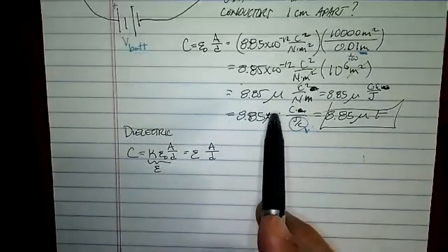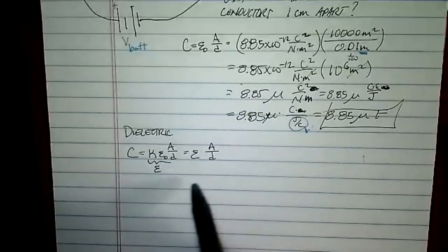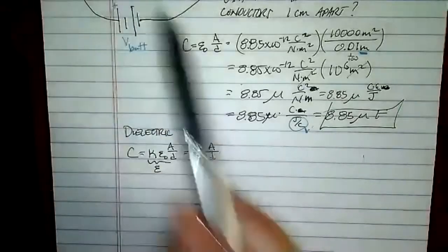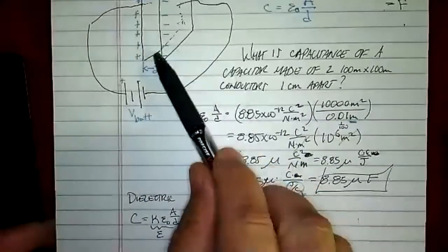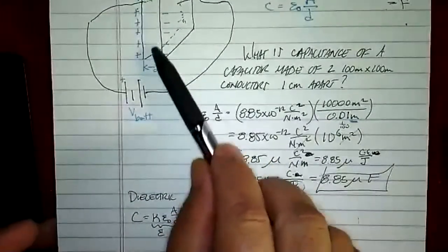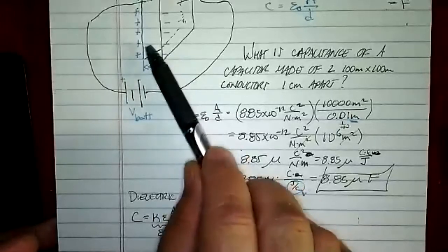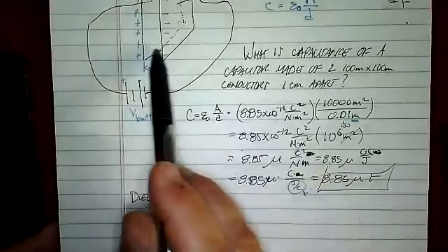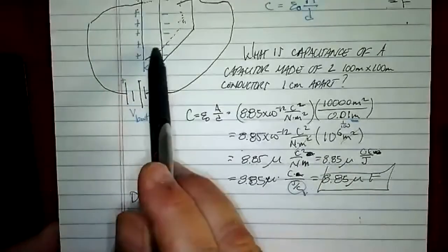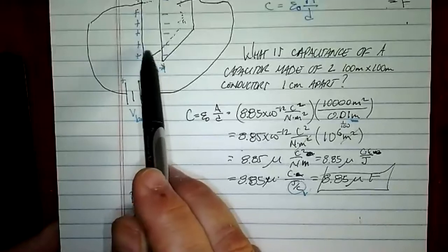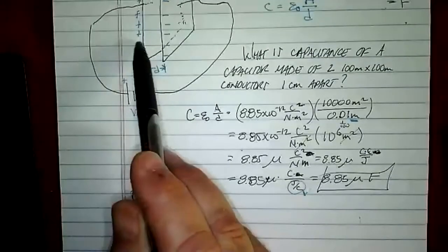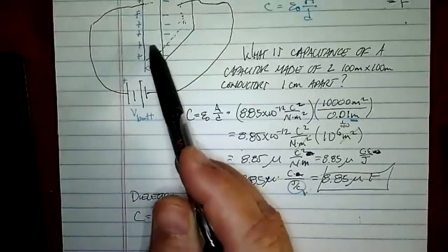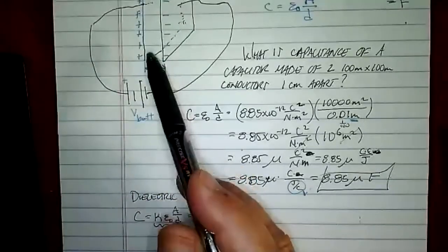So yeah, you can actually make it a lot better, meaning it can not only act as a mechanical barrier to keep the two plates from getting squished together, by filling it with neoprene or polystyrene or something like that. So it helps that way. But not only that, air has a breakdown voltage of about 3 million volts per meter, meaning if you have a meter separating two plates, it takes 3 million volts for lightning to strike across it.